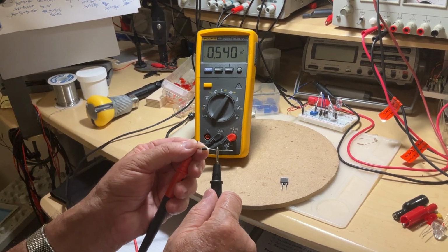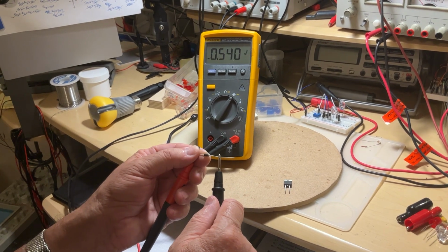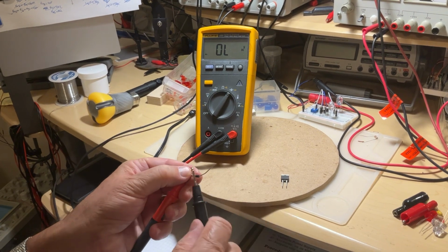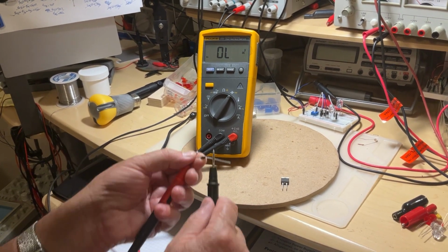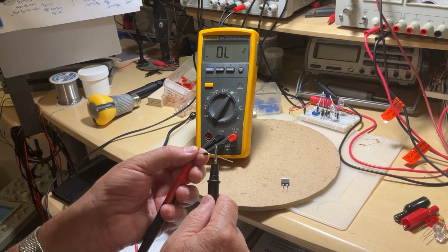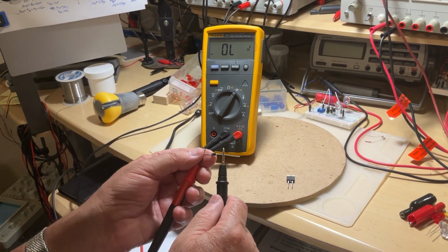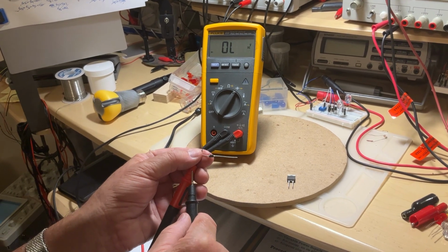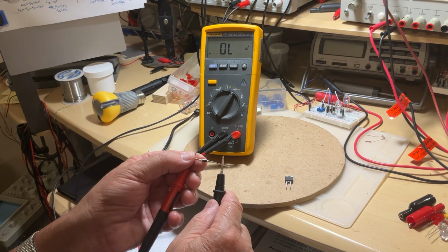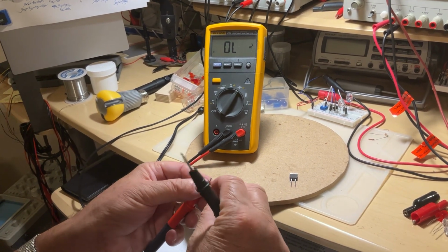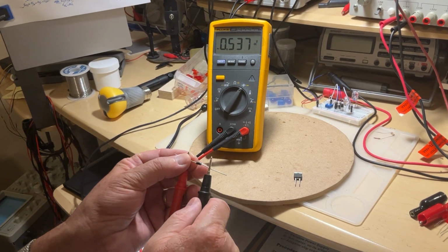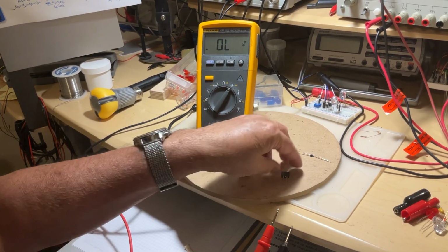So now I'm energizing the diode in such a way that it's conducting. This is why I can see some indication. If I put it the opposite way, the diode won't conduct, so my meter is going to show me overload or infinite value, like an open circuit. Open circuit, because now the cathode is aligned to the red of the meter, and the anode is aligned to the black of the meter. In order for a diode to conduct, it has to be aligned with the anode to the red and the cathode to the black.